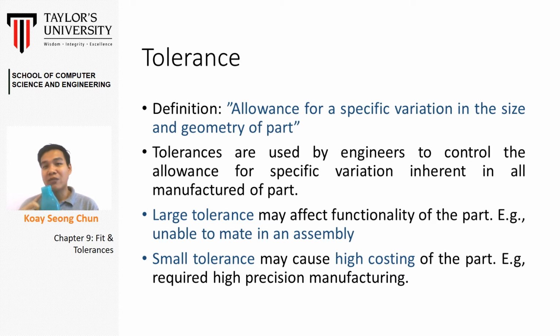If I have a very large tolerance, when I fit these two components together and fill in water, because of the large tolerance the gap between these two components will be very big, and it may cause leaking. So a large tolerance is sometimes not good for assembly.